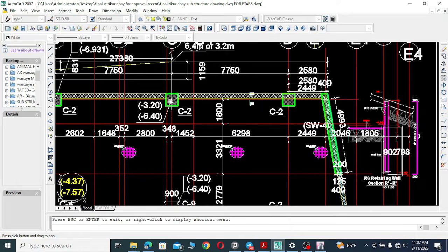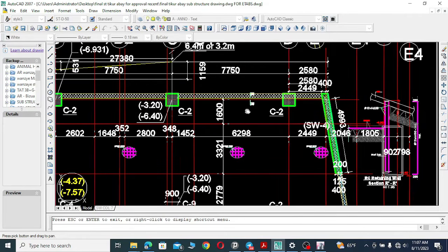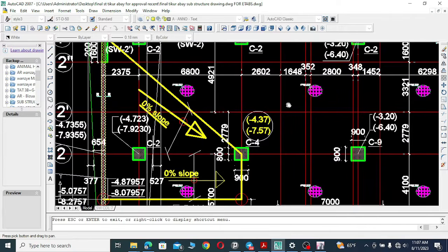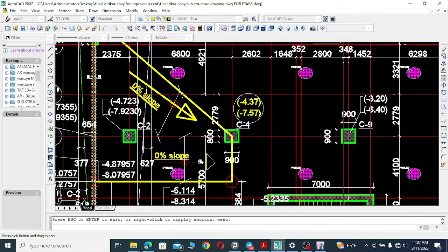So we can use the rigid connectivity here, but later it will create instability problems during the dynamic analysis. The difference in locating the center line of the retaining wall, aligned with the center line of the columns, and just providing some eccentricity is insignificant. So having this in mind, we can consider all the structural members to be concentric to each other.